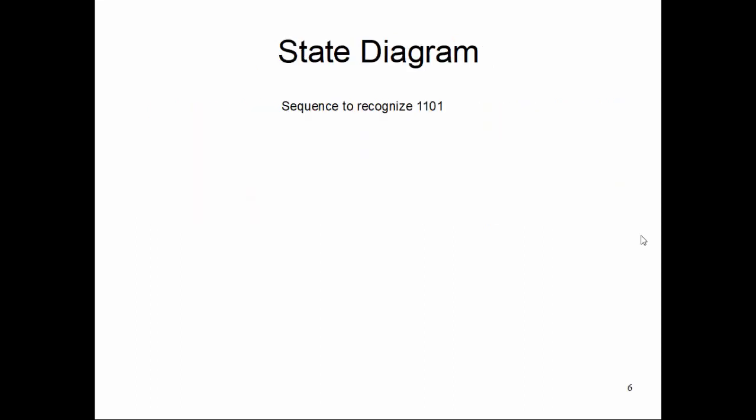Now let's make a state diagram, a formulation of that whole problem in a more formal way. Let's say I define a state called A, and upon reset the whole machine goes to state A. How the state is implemented, what the digital implication is, that's a different thing. But somehow we can mark in a machine a state called A, and upon reset that digital machine goes into state A.